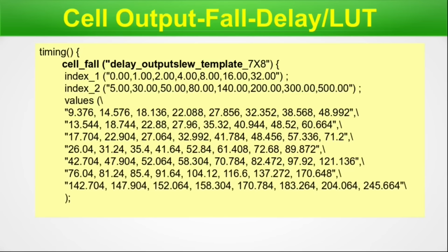Now why am I showing all these explicit examples? Because in our actual .lib file, that is the Liberty timing file, all these kinds of various lookup tables will be present. I am knocking it into your mind with the example, so that you remember when you open and read a .lib file and you don't feel lost in the data.